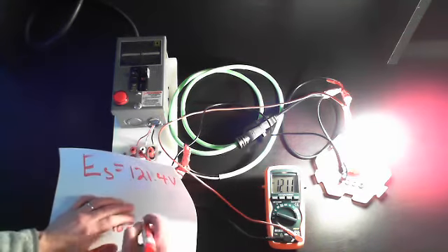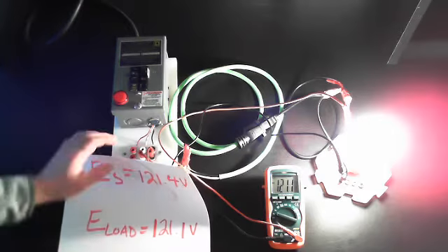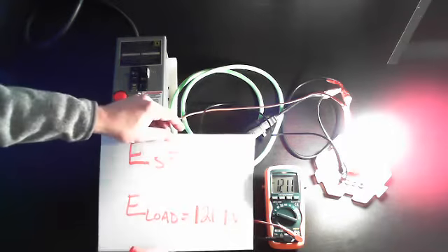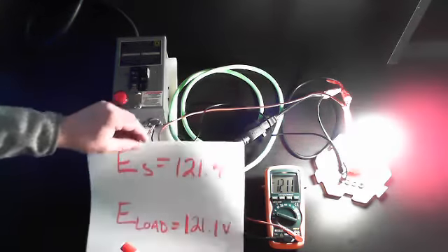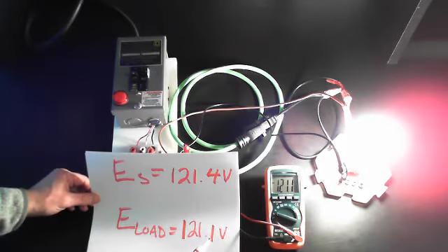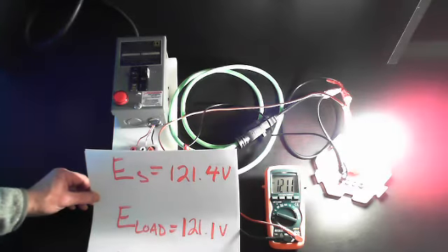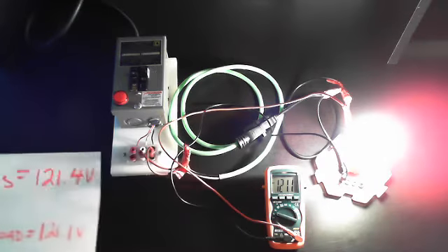Of course, we only have one connection, a very minimal amount of actual length of conductor. And of course, it is a difference, right? So we can see that there is less voltage at the load now than at the source, but it's marginal. So now we'll plug in a 50-foot extension cord.